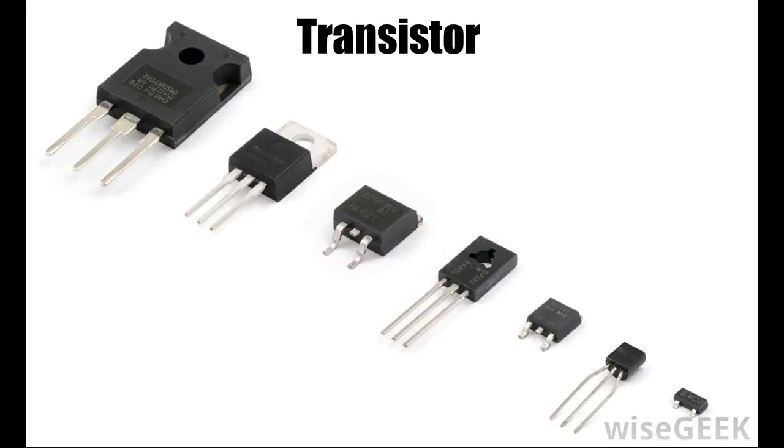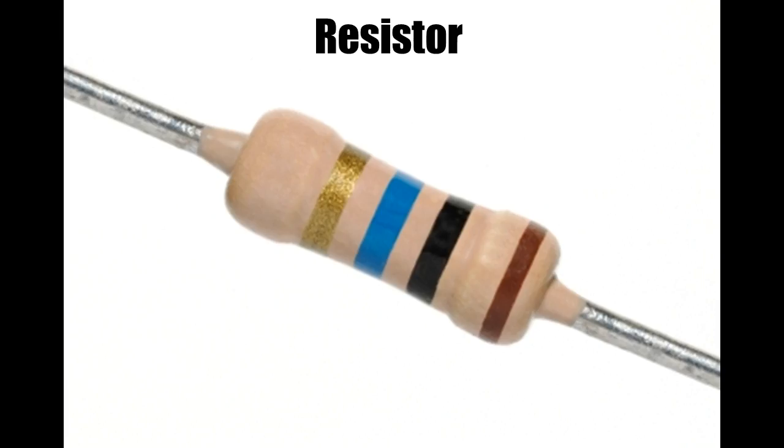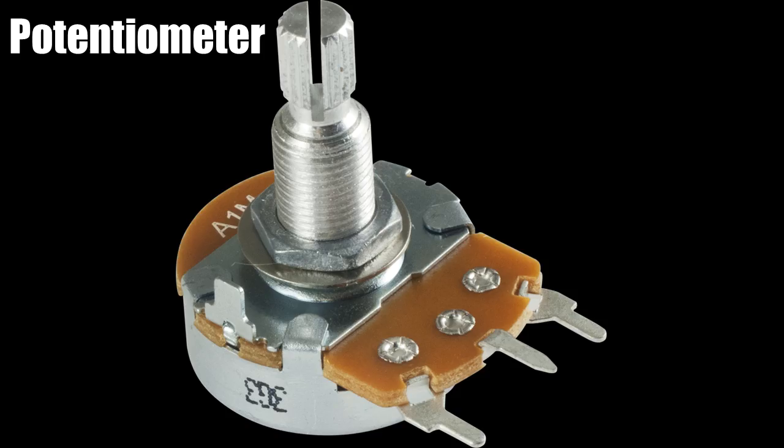Transistors are a semiconducting material that can switch the electrical current between different points. Resistors are small components made of metal oxide film that are insulated. They apply resistance to the circuit and reduce the amount of energy to values useful to other components. A potentiometer can be treated as a variable value resistor. It consists of a high resistance material and a rotating armature. When the knob is turned, the armature contacts the higher resistance material in different areas, resulting in adjustable resistance values.